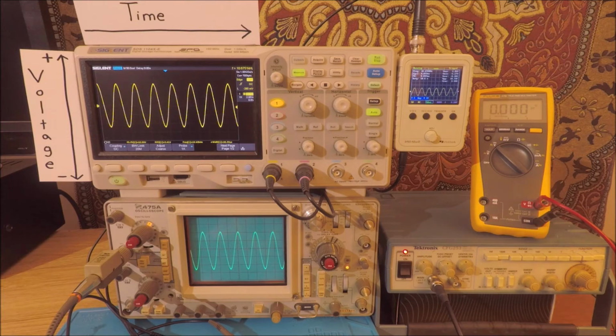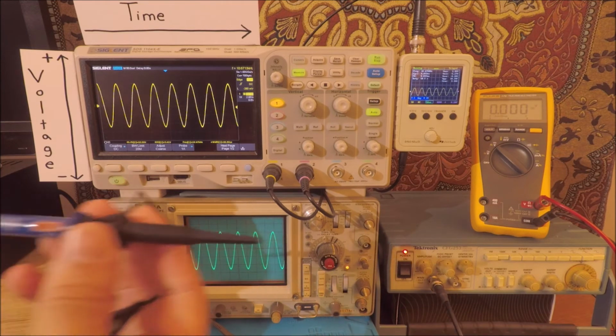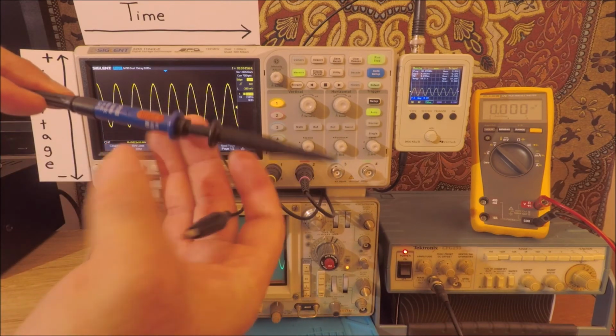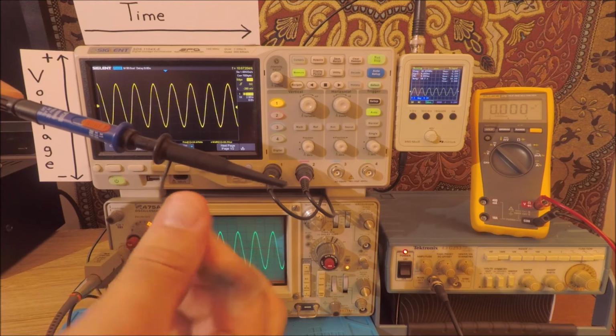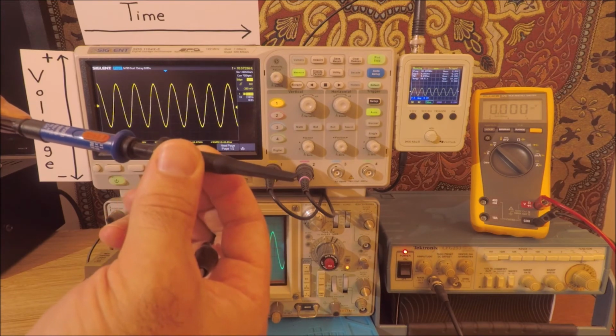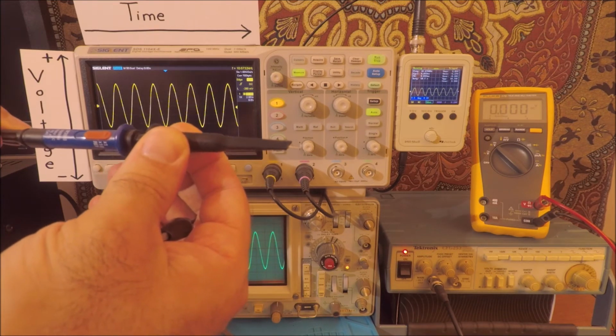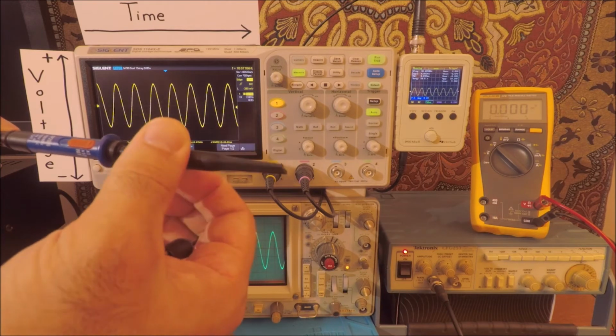And that pass band is going to be defined by several things in the oscilloscope. The first thing is actually not inside the scope. It's going to be the probe itself. So in a typical oscilloscope probe like this, you'll have the ground clip lead, and we'll have the hat here that has a small clip, very handy for latching onto a circuit.